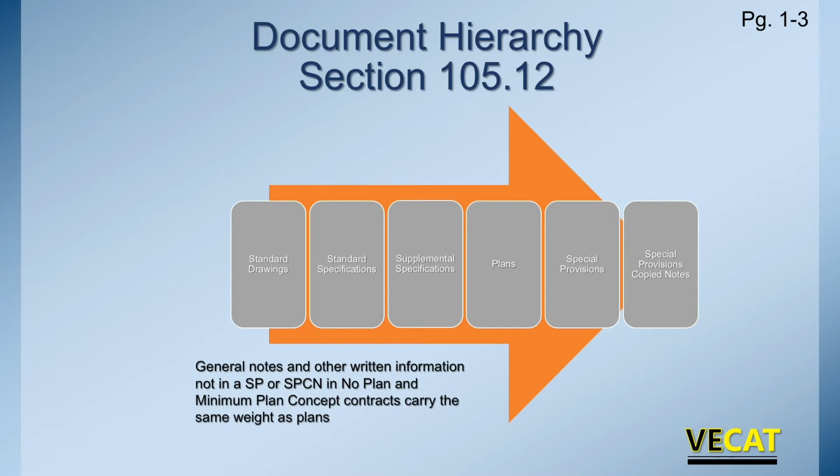If there's notes, typically this will be in a mini plan or in a plant mix schedule. If there's some notes that may change your material specs, it has the same weight as plans, so it'll overwrite your supplementals and your standard specs.